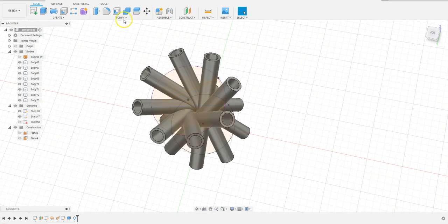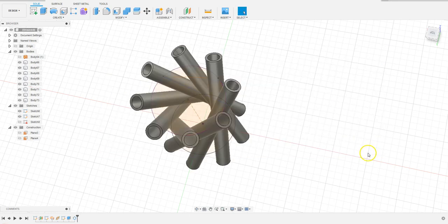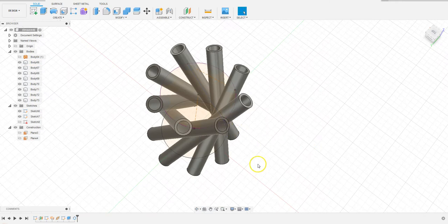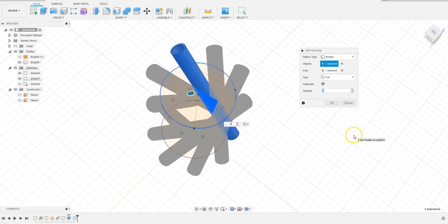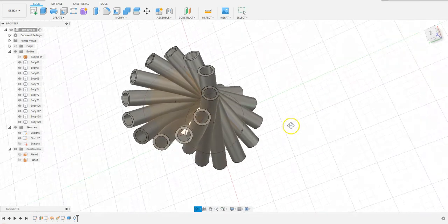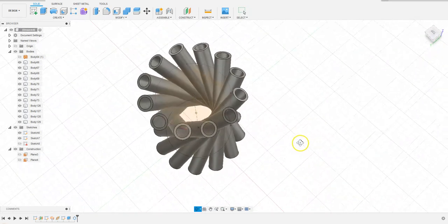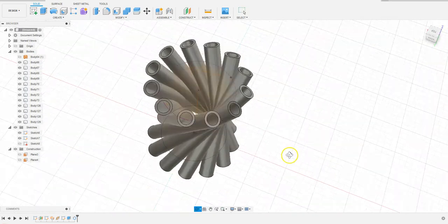Maybe we can go back and change the angle, the skew angle. What if we try 32 degrees? Let's see what happens. Now, do we have? Yeah, looks like we can see through, right? So we can put a pencil in it. Play with it and see how many pencils you can put there. Make sure the hole is big enough. If 8 is too small, try 8.5 or 9. Let's try 12. Can we all see through? Yeah, I see there's something there. Make sure the circle is big enough and the angle is not too big, so that we can put things in it if you want to.